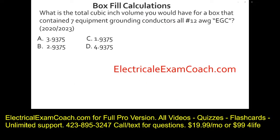What is the total cubic inch volume you would have for a box that contained 7 equipment grounding conductors, all of the 12 gauge persuasion in the 2020 and the 2023? I left out all other conductors because you're going to use the same rules: after you do this calculation, you group it with whatever the largest conductor is in the box, like you learned previously.